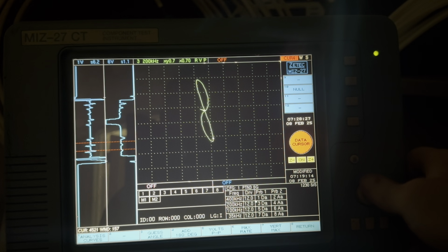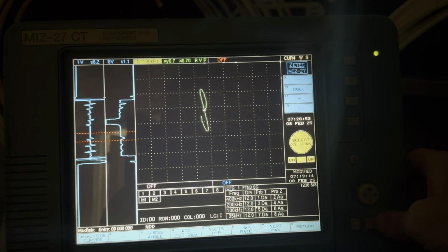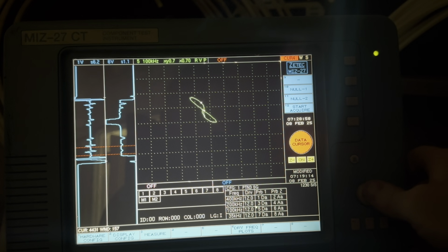Okay, let's go up to the 20s. The phase lag on channel 1, which is 400 kilohertz, was probably 20, 30 degrees more phase spread than this. This one has less phase lag because the lower frequency, 200 kilohertz, penetrates quicker through the material, or the eddy currents do. So in this vein, let's go to channel 5, even less phase lag. We'll go back to the 100%. Still, it's set to about 40, but the phase spread between the 100%, which is right there, and the 20s, that's only like 40 degrees of phase spread.